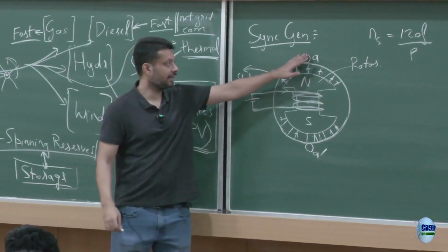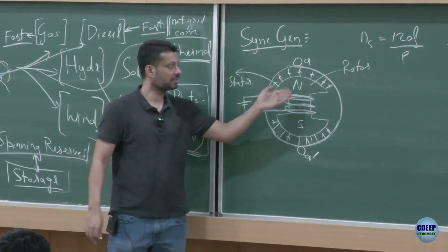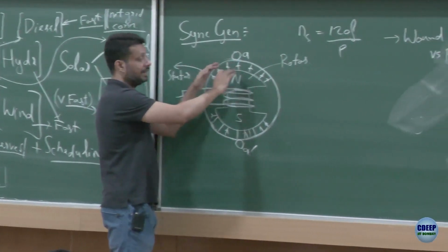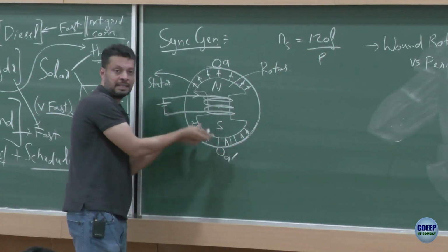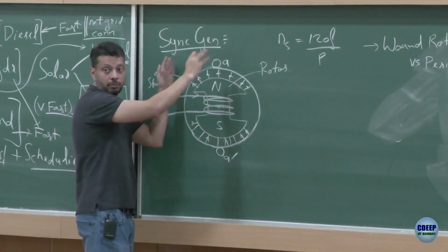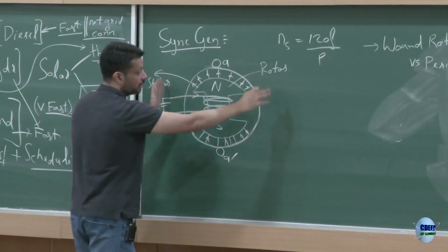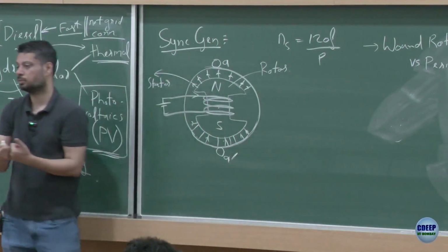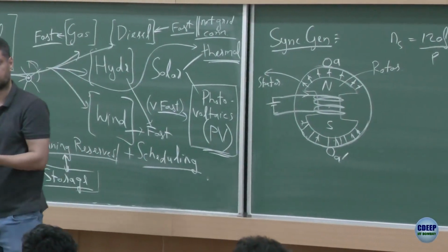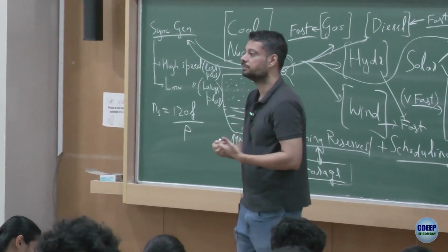There is no current here; only in the rotor I am giving a DC current, so it is producing flux and it is going like this, and then through the yoke, through the remaining stator, it is coming back and then again going back from here. You remember the geometry? So the flux is crossing the air gap from rotor to stator, in the stator it will go back through the yoke and then come back and enter from the south pole, right? Any questions so far?